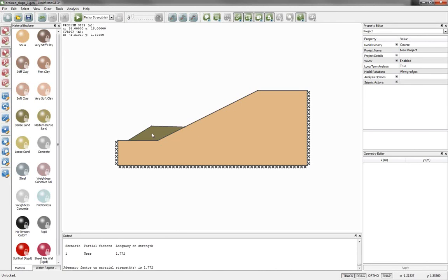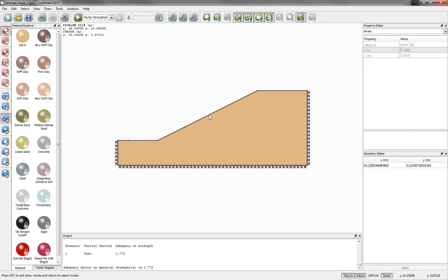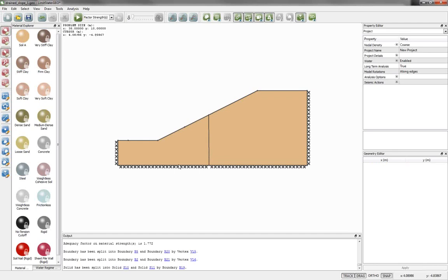Now, you may decide that this berm is not the right solution, and that perhaps it would be better to try maybe a sheet pile wall or some piling. So we can look at what might happen, just to keep it simple. If we put some sheet pile walling down the middle of the slope, so just draw an almost vertical line there, put in a base there.